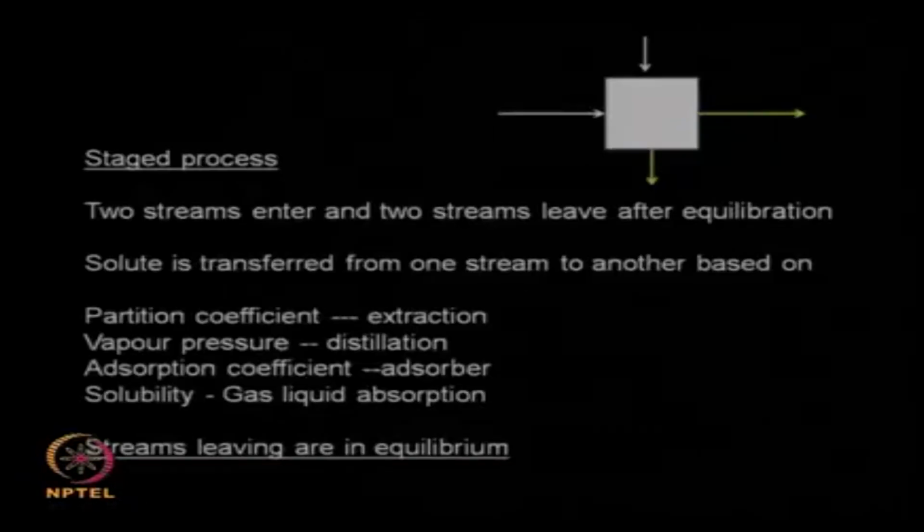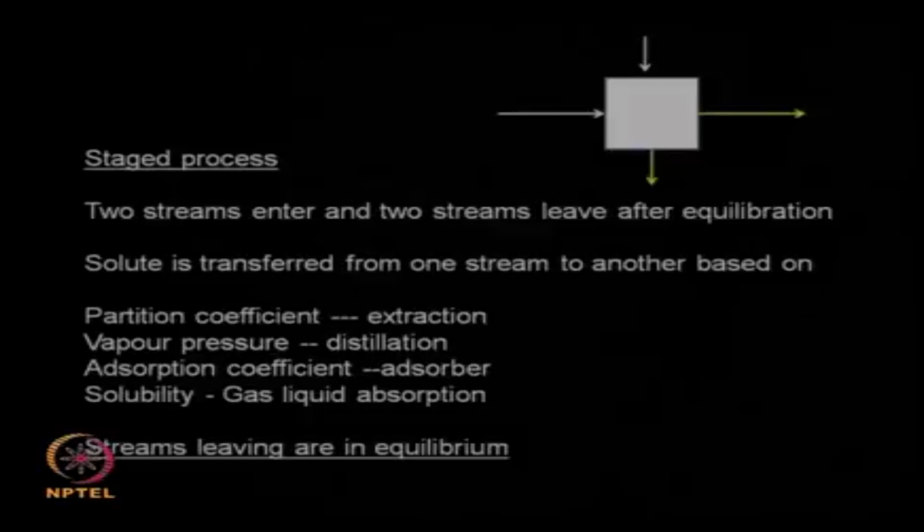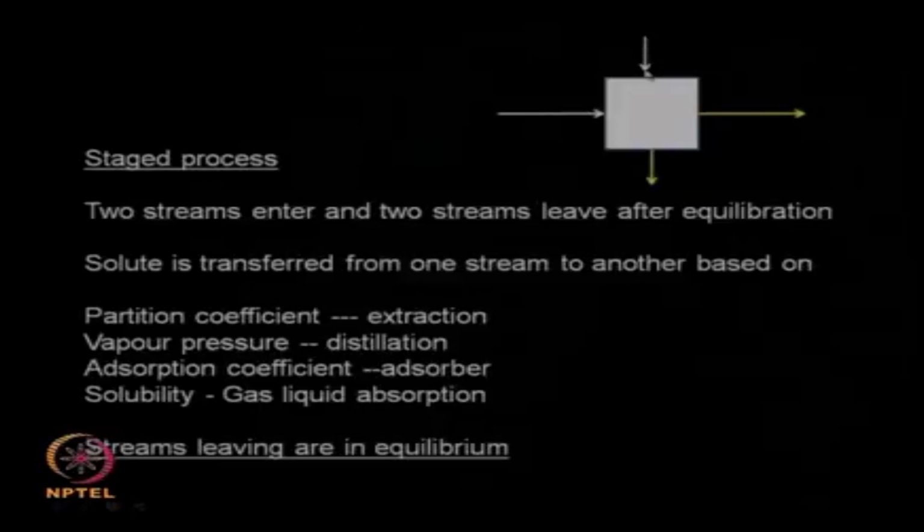Now we have been talking for some time on something very important, that is called stage processes or a stage process. That means we assume an adsorption taking place in a single stage, we have a feed solution containing the solute, we have the adsorbent added here either in the form of a fresh adsorbent or already containing some adsorbate, and then two streams are leaving.